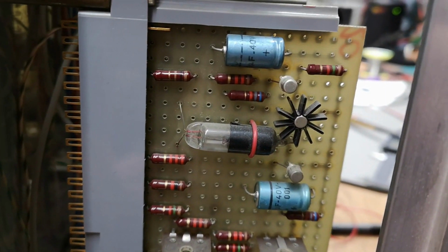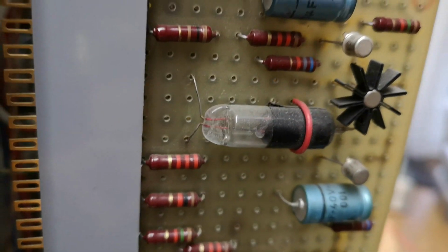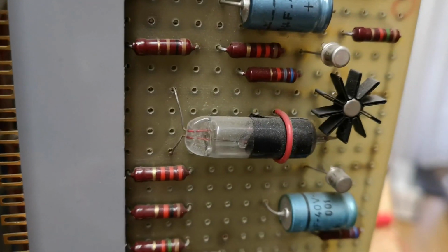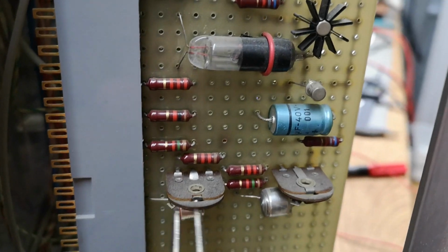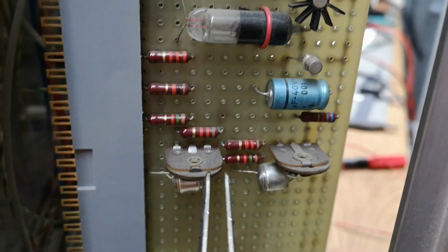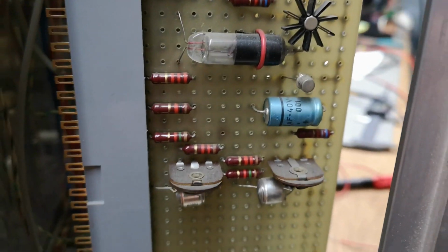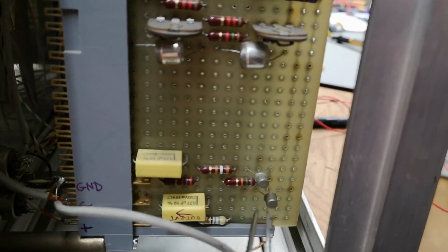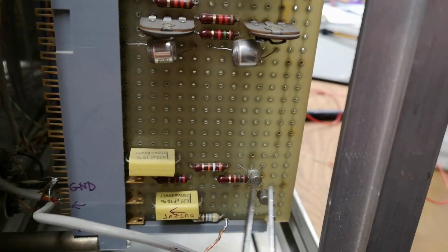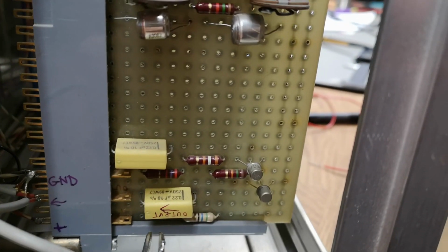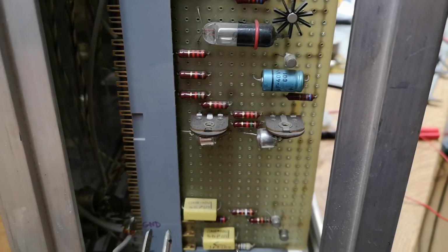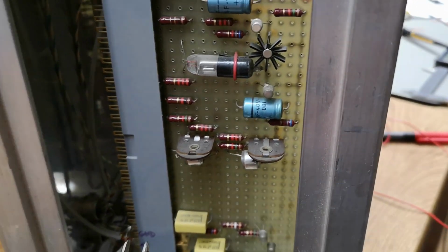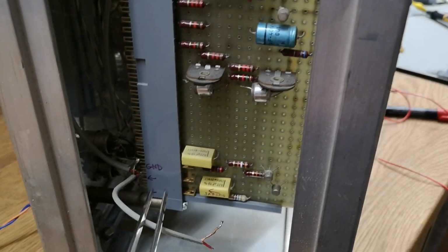And as you can see, this is a sine wave oscillator. This is the classic bulb amplitude compensation. And those two trimmers, they do the frequency and the compensation circuit. And this is the output amplifier. And this generator makes a perfect 7.8 kilohertz sine wave constantly.